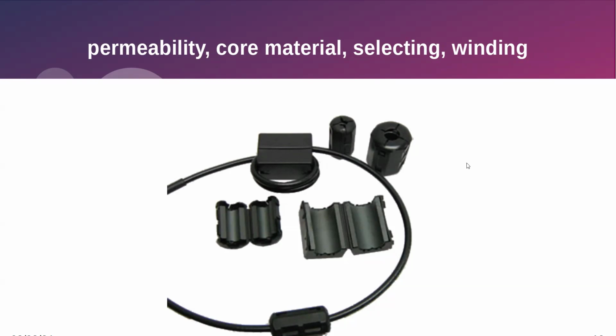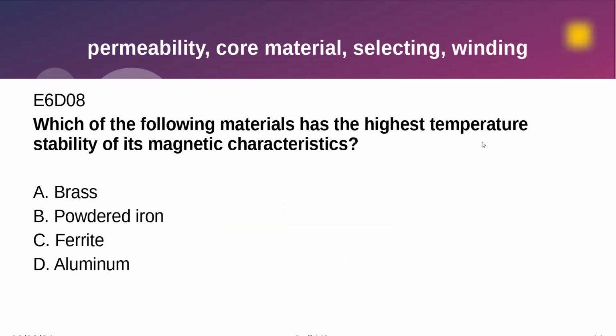You can't really have too many ferrite beads or clip-ons. Put them on anything that's got a cable: any of your audio type stuff, microphone cables, USB cables. The USB cables you buy with those ferrites on them cost quite a bit more.